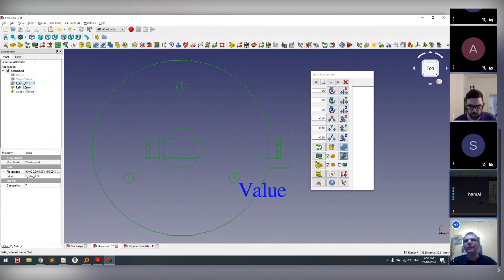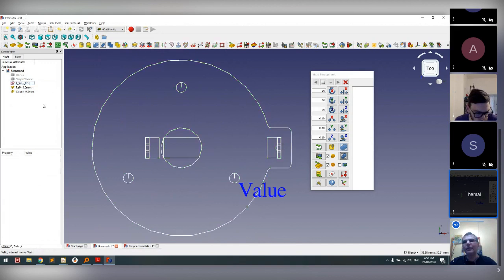So essentially, Drew, once you have that, the first step is done: create an object, but that's not really a sketch per se. Then you have to do another operation that takes the object and makes it into a sketch consisting of lines and arcs and stuff. I've selected shape 2D view. Then what's the next thing I click on? The icon next to it: 2D object to sketch. So you're taking a 3D object and creating a 2D object out of it, and then taking the 2D object and making a sketch out of it. Those are the steps. And then what do we convert the sketch to?